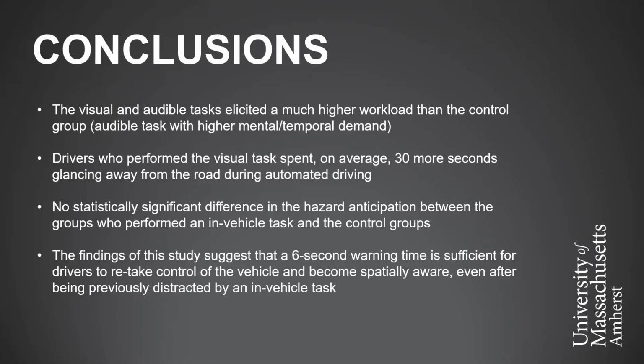And then overall, tying it all back together, what Cole mentioned at the beginning of the presentation, looking at the 6-second warning time and whether it is sufficient, we found that it is sufficient for the drivers, regardless of their in-vehicle task or distraction, however you want to call it. It still presented them ample time to perceive the hazard and to retake control of the vehicle before that hazard came into play. So the 6-second warning time was sufficient as a conclusion of this study.